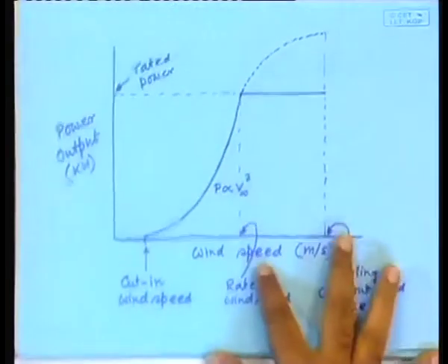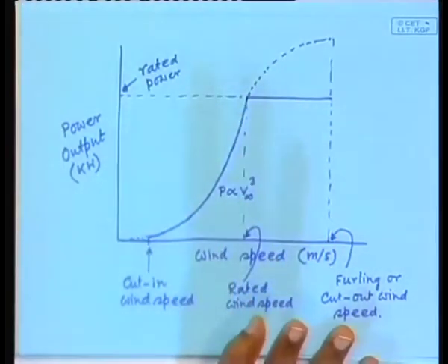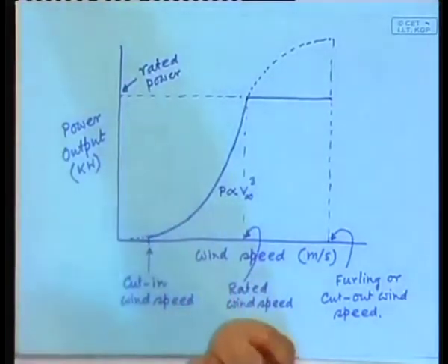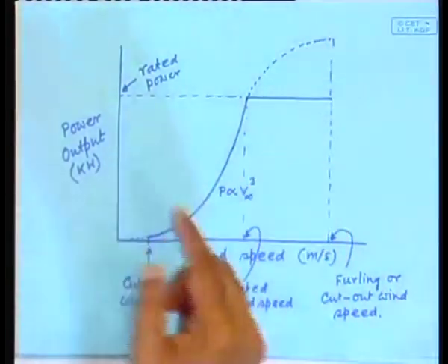Okay, so we have more or less understood what can be done here in order to obtain the maximum power output. Again, to repeat, we have essentially two levers in hand. One, the pitch angle control, which controls the mechanical power input. Two, the power electronic control that controls the electrical power output, and with that you ultimately obtain this. The logic for controlling the pitch angle should be to keep the pitch angle constant at the optimal value, and the logic for varying the power output through the electrical means should be to obtain the maximum power point in the CP TSR characteristics.